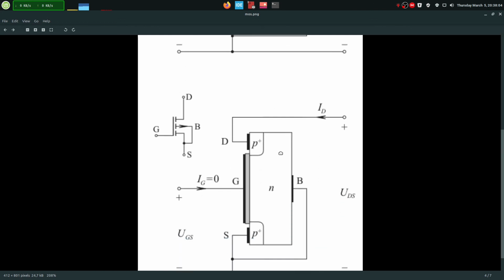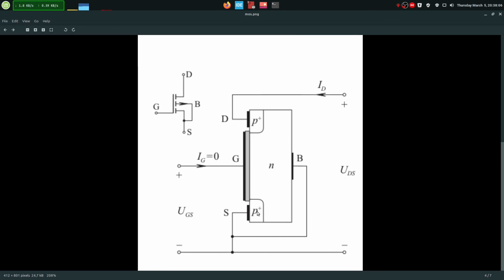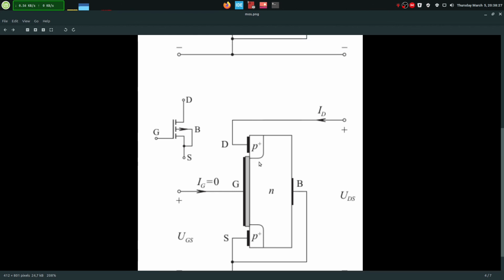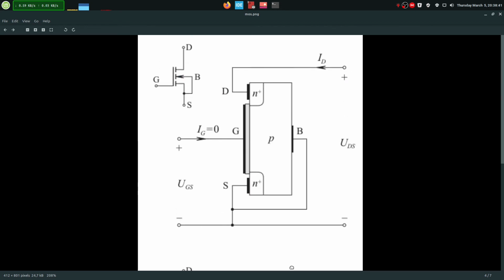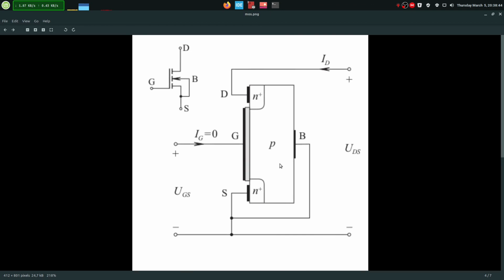The same can be said for the P-type. In this case, it's a channel of holes, or the lack of electrons, which is the majority carrier. And this is just a fun fact. This is why N-channel MOSFETs are more available and have better characteristics, at least in current and dissipation, because electrons are way better conductors than holes, because their mobility is much greater, I think around 3 times. This is why P-types usually dissipate more power and have higher resistances even when turned on. Same for NPN and PNP, but that's beside the point. This is just a fun fact because I would like to show you the whole picture.